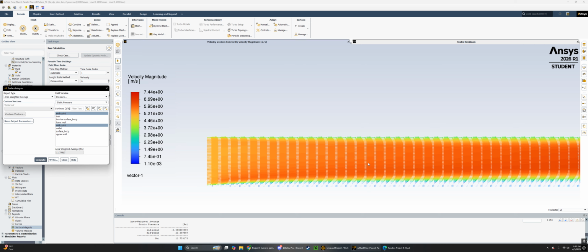So the distance between them is half of the length of the pipe, so that's 225 millimeters. So if we take these two values, negative 0.0832 minus 23.5896, and you get negative 23.6728, and then divide that by 0.225. That's going to give us negative 105.21. So that's the pressure gradient we got from Fluent.